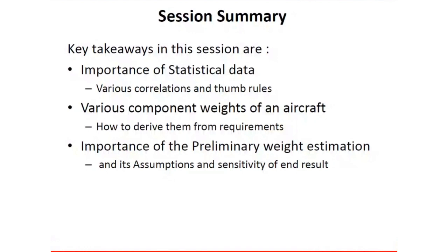Various component weights of the aircraft are also part of the statistics, where you can, for example, look at Airbus or Boeing and see the total weight and the wing weight percentage, and that is something which will also give you an idea. The importance of preliminary weight estimation cannot be overemphasized, and of course you also have to look at the assumptions you have made and the sensitivity of the end results.